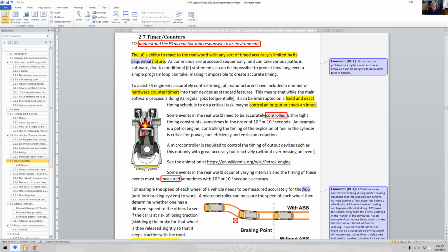And if it happens after the piston has got to the top of the cylinder, then it's a bit late actually. So you want the spark to happen so that the fuel has got time to ignite, just as the piston is about to go back down again. You want that massive amount of explosive power to happen right critically then. And this happens in a car which is revving at 10,000 RPM. You can imagine that this has to happen at very, very defined timing, perhaps down to microseconds, or maybe even less than a microsecond accuracy.